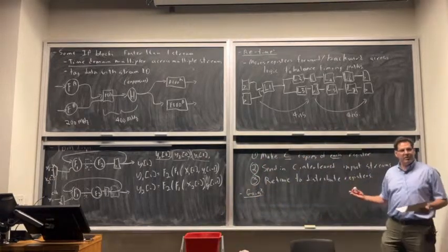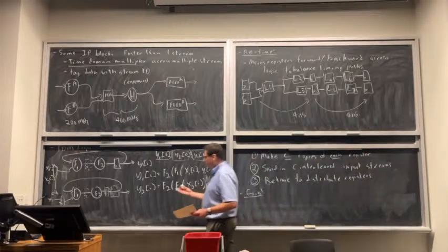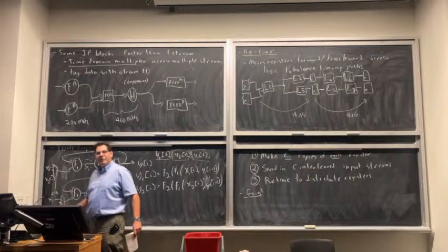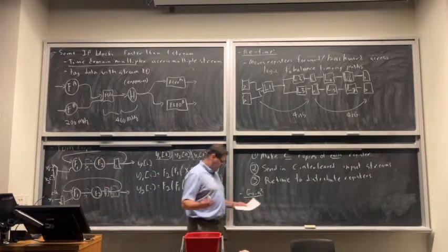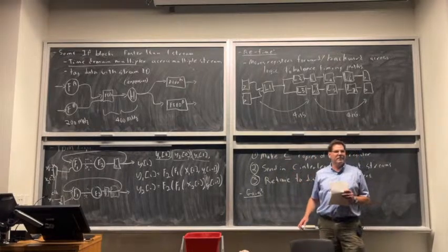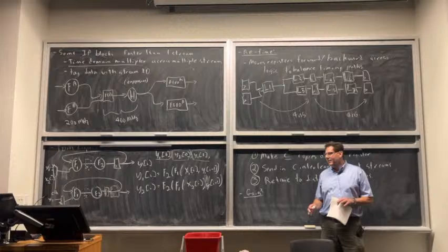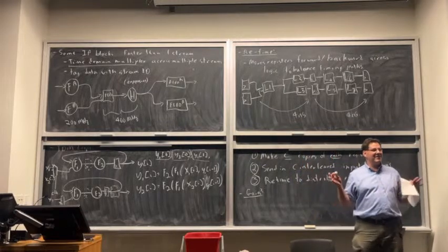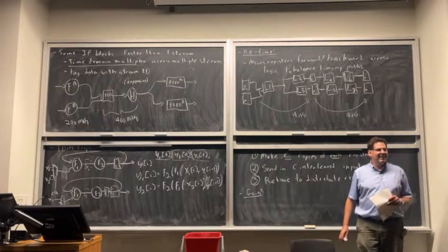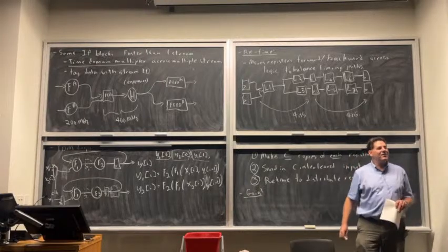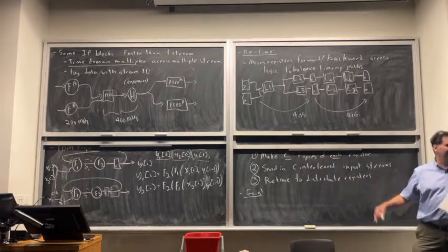So the registers are pretty cheap in an FPGA. So I did add some registers, but that's pretty cheap. Add a little bit of muxing, but probably not much. So I haven't added very much area. Can I clock this faster? Assuming that I really retimed nicely, how much faster can I clock? What do you think? There's only one constant here, so there's not that many guesses that you could have. So maybe this is so easy, you're like, there's no honor in this. You just put the class out of its misery. How much faster can I clock this? What do you think?